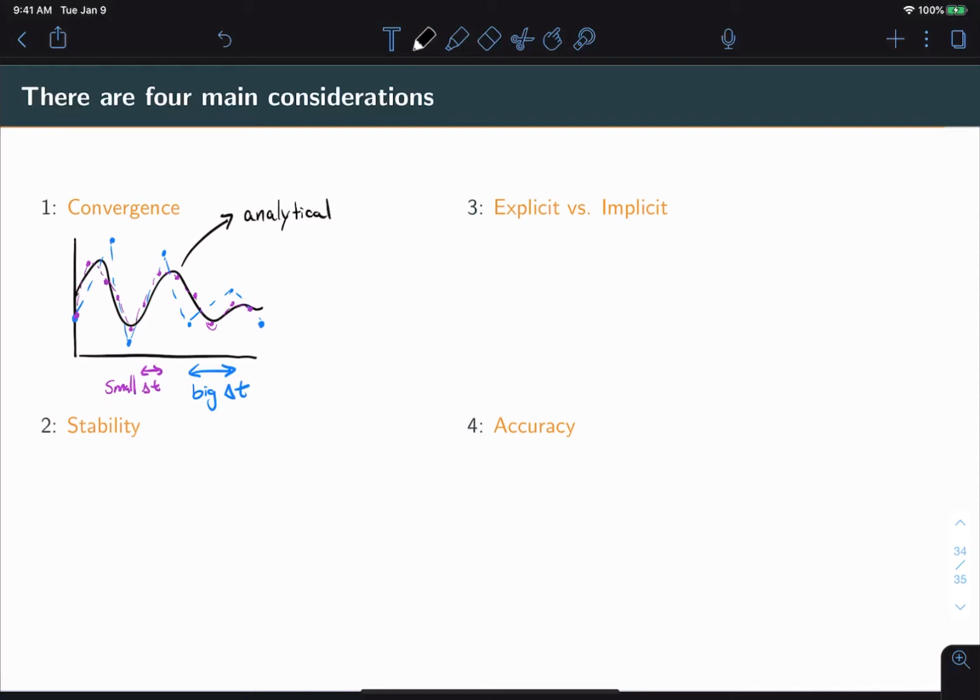In the case of stability, it is important to consider that some algorithms will simply blow up if delta t gets too large. So there is typically a threshold for each algorithm below which you will get a stable solution. For example, for Newmark's linear acceleration, the ratio delta t over Tn, the natural period, must be less than or equal to 0.551 for the algorithm to be stable.